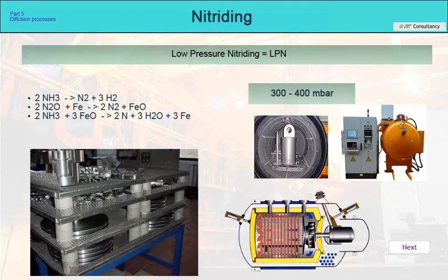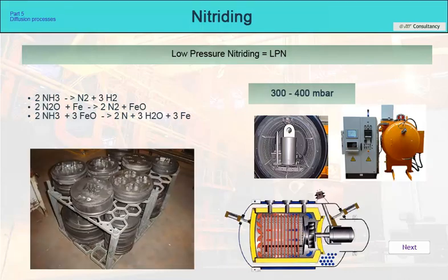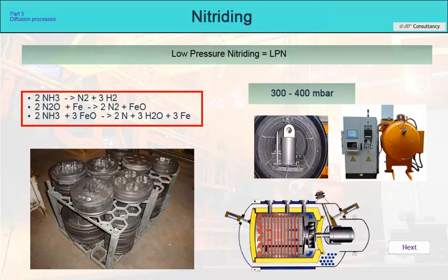The working gases are fed directly in front of the convection fan, and thus ensure a good distribution within the work area. In terms of results and reproducibility, it is a very good solution that, like all methods of nitriding, has certain pitfalls. Considering that atomic nitrogen for diffusion is obtained by reactions through iron oxides, this process cannot be used for nitriding for duplex coatings.